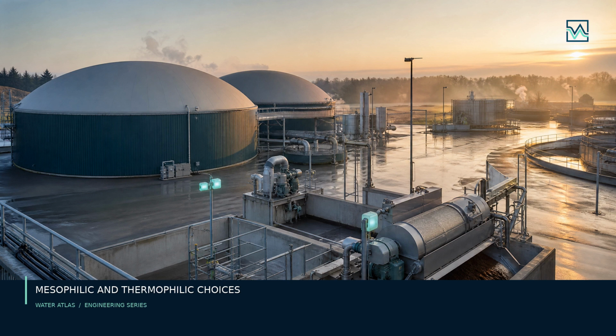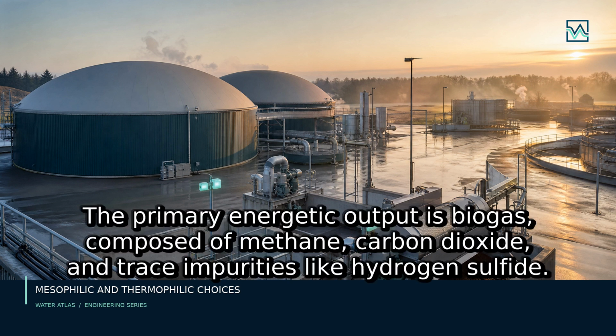Unchecked siloxanes combust into abrasive silica ash that destroys internal combustion engine valves and turbine blades, underscoring the necessity of robust gas scrubbing.